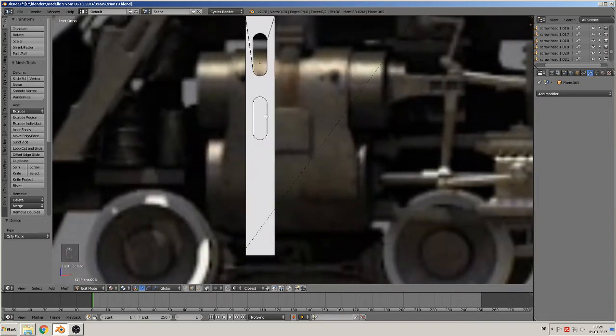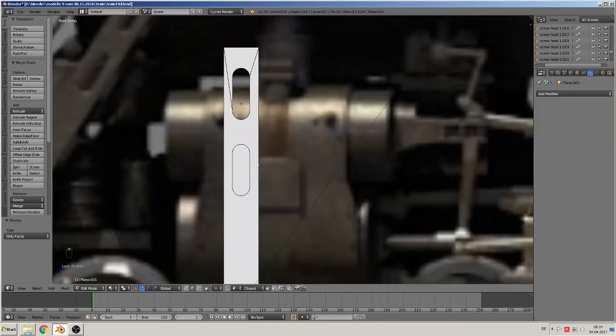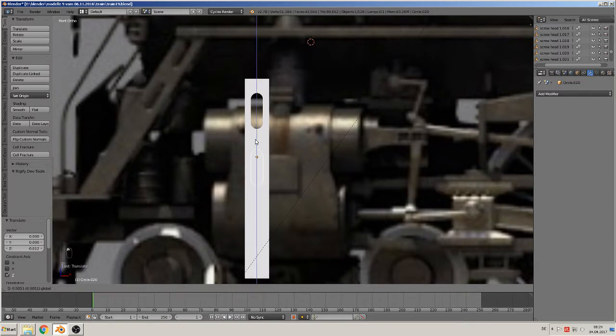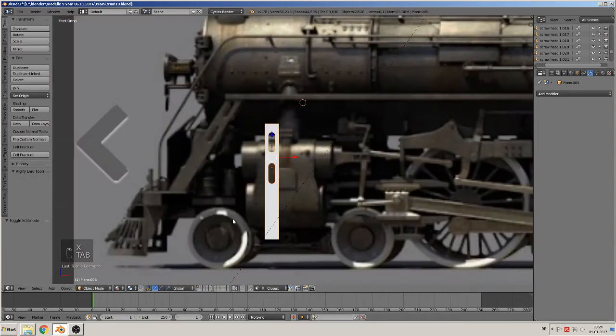Then we position the next one that is there, and can go a little bit deeper so that it can be cut at all. So we are here. I'll first mark this thing, then the other thing, and now edit mode, select all, and knife project. Now we can say X only faces, and it's open.